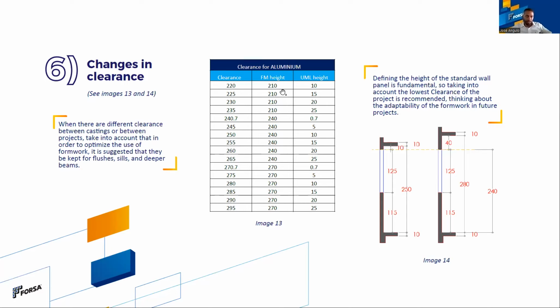After that, if I go, for example, to 2.65 meters, in this case 265 centimeters, I'm going to use this 240 centimeters panel instead of the 210 centimeters, because this one is a standard and covers a little bit more area than the one before.